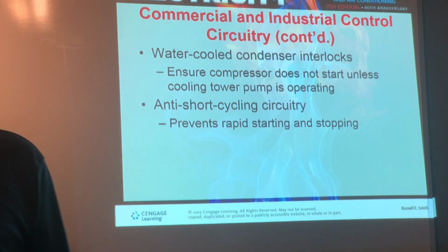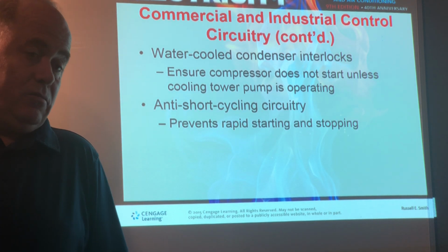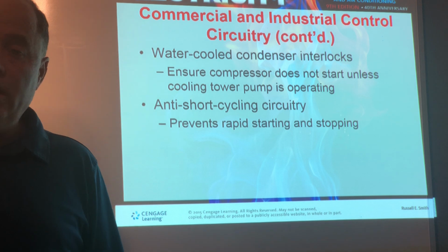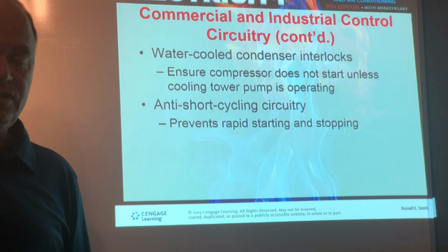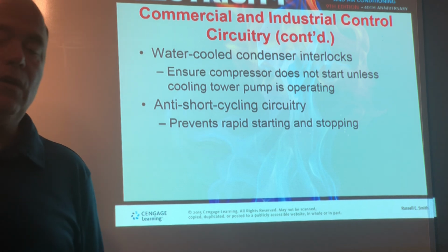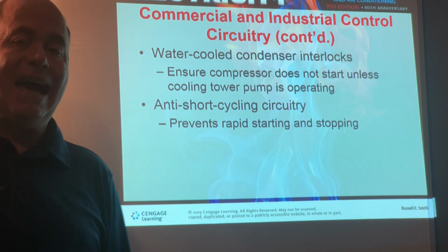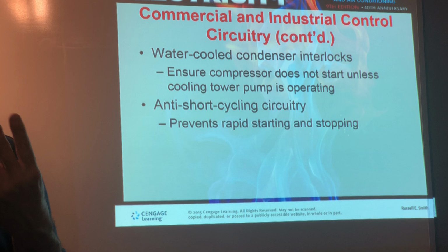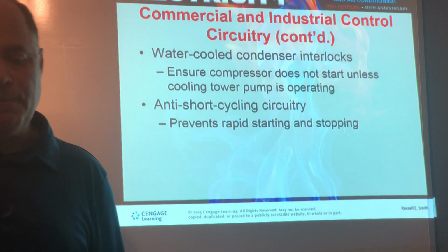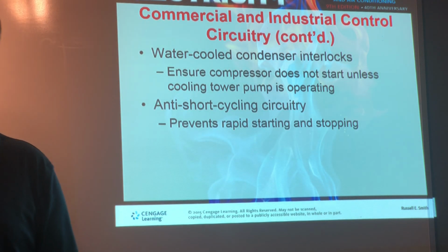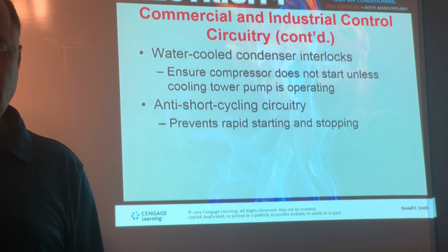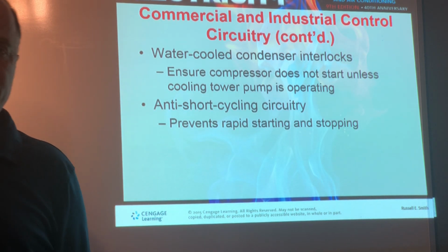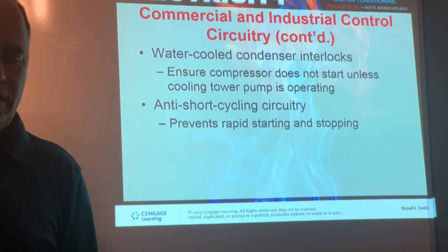Or you might just have a centrifugal chiller that has 2,000-3,000 tons, where you have this condenser water, and we use water to cool the condenser, which is typical, and then we put it through a cooling tower, and that cooling tower serves that centrifugal, or maybe 2 giant centrifugals. So water-cooled is a big part of commercial and industrial equipment, and I do whole lectures on that. You can look for that in my other classes.